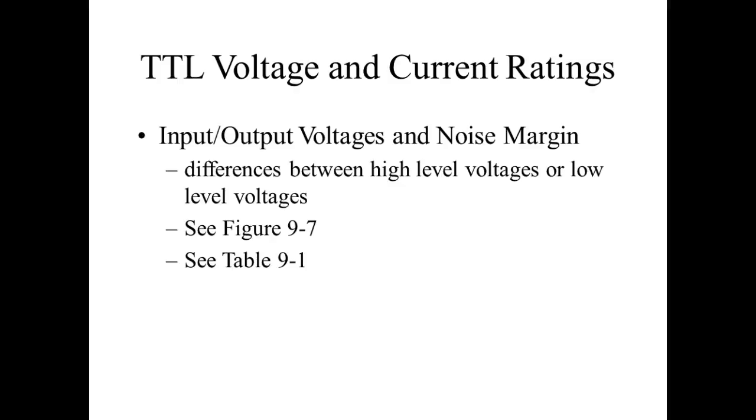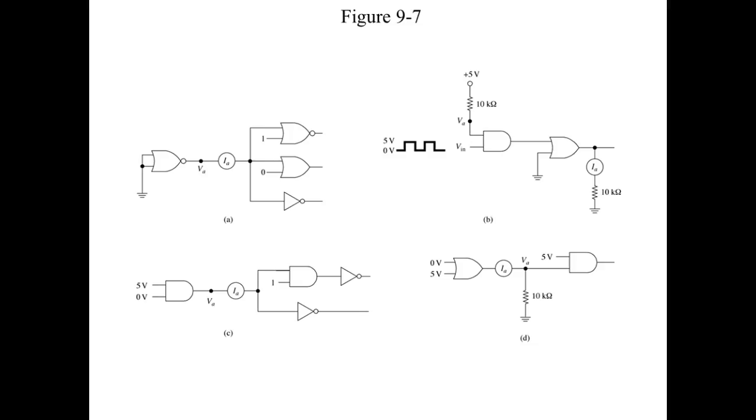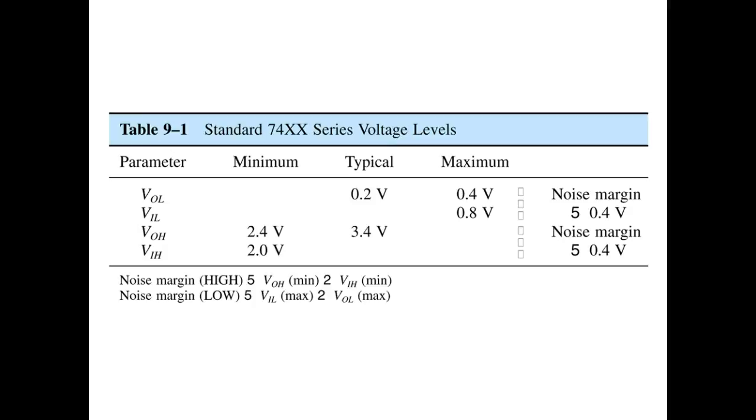And that's generic. When we start looking at these data sheets, this will be fan out, guys. We're looking at V out low, V in low, V out high, and V in high. Notice standard is V out high, worst case. We need to get above 2.4, but that's worst case, right? Typically for TTL it's around 3.4. And the maximum output for a low is 400 millivolts.